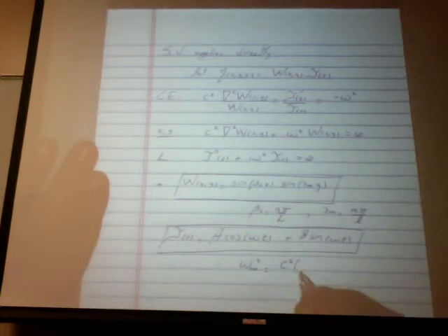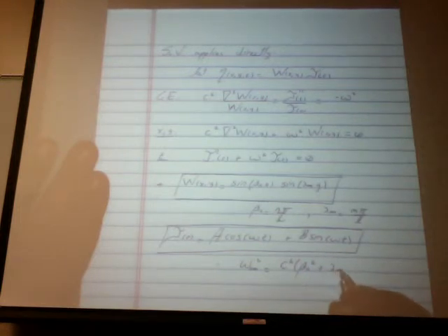And that's why we call that omega, because actually those are the frequencies of vibrations of that membrane. Such that omega nm squared is equal to c squared times beta n squared plus lambda m squared.